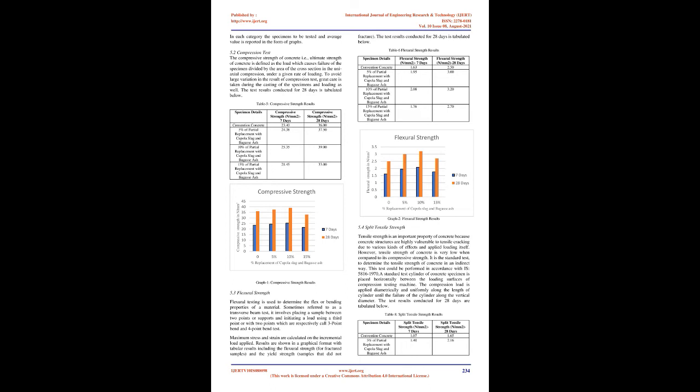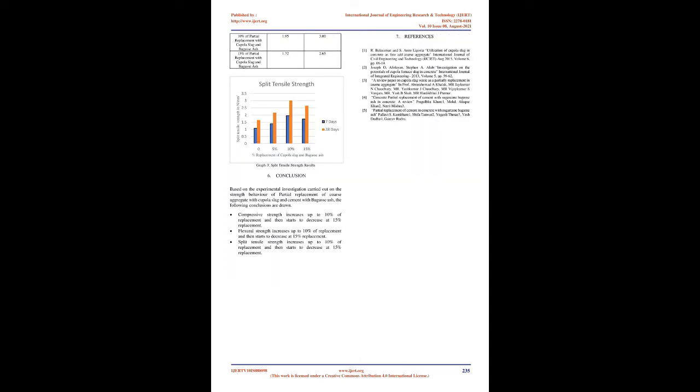Although the silicate content may vary from ash to ash depending on the burning conditions and other properties of the raw materials including the soil on which the sugarcane is grown, it has been reported that the silicate undergoes a pozzolanic reaction with the hydration products of the cement and results in a reduction of the free lime in the concrete.